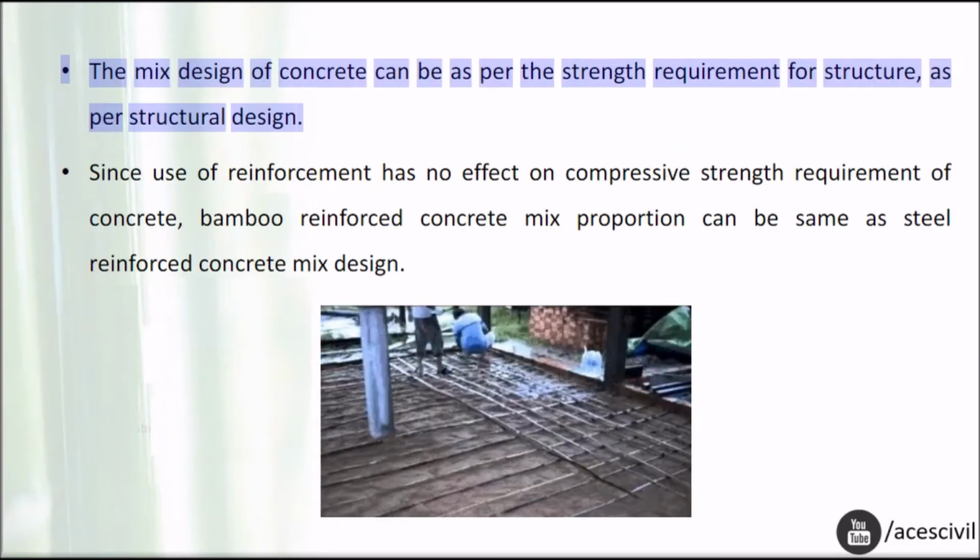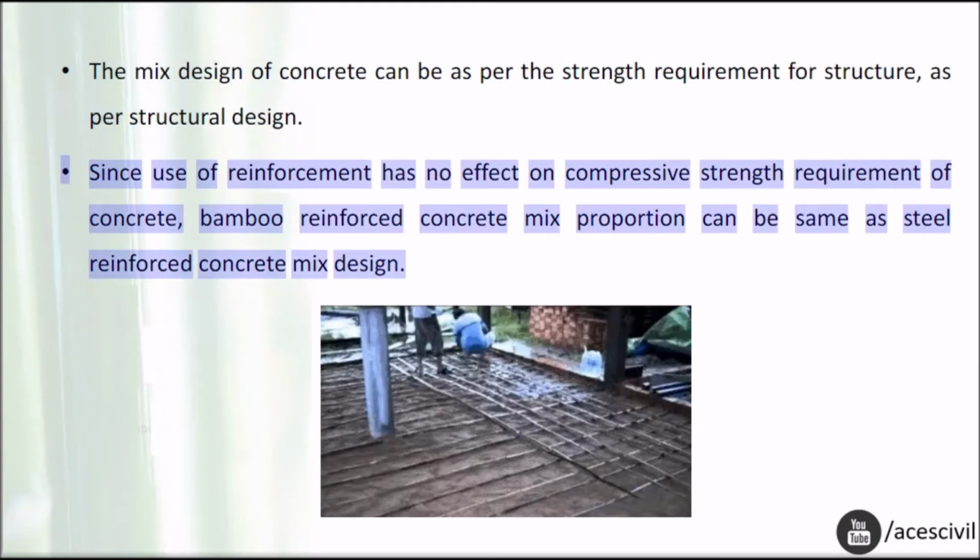The mix design of concrete can be as per the strength requirement for structure, as per structural design. Since use of reinforcement has no effect on compressive strength requirement of concrete, bamboo reinforced concrete mix proportion can be same as steel reinforced concrete mix design.